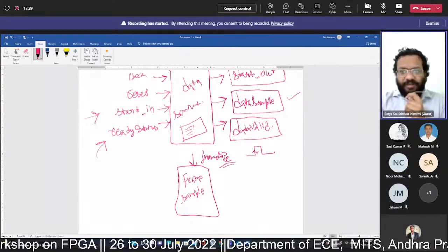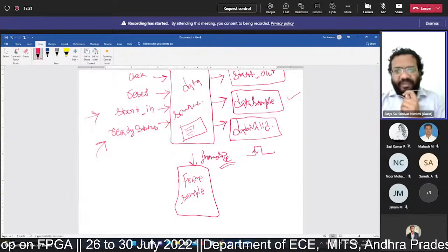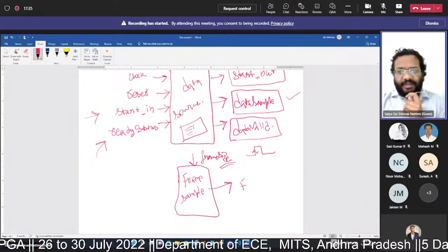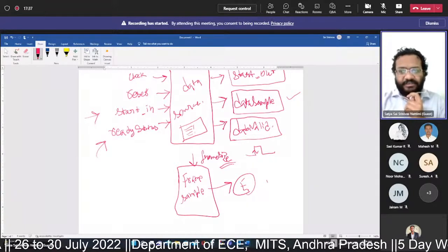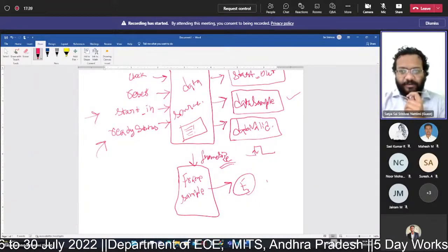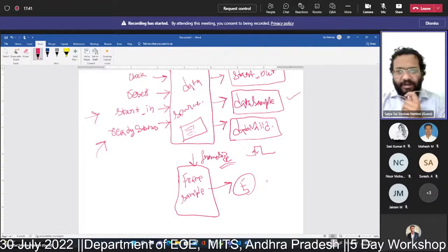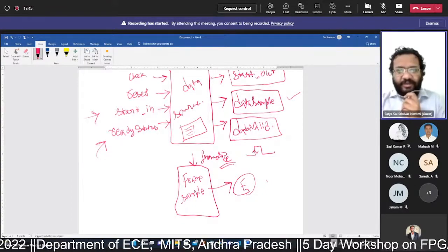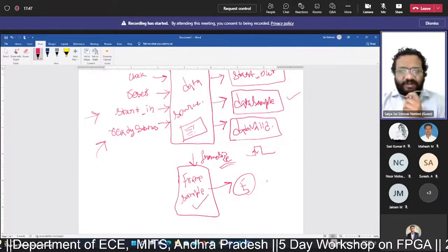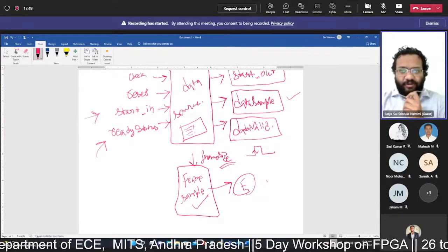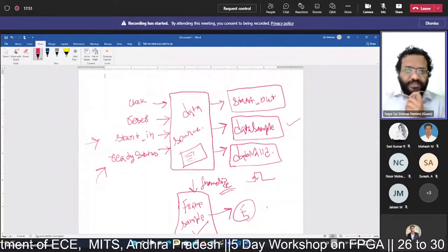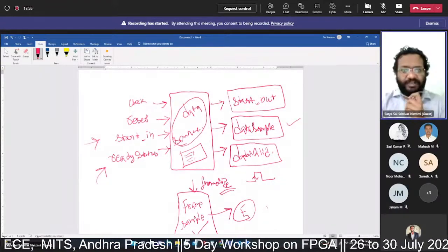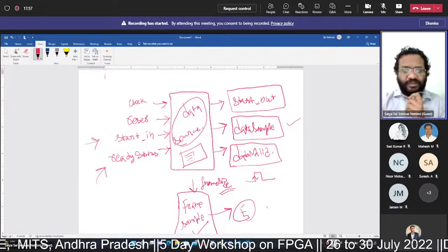Depending on the frame size, it collects that many samples and calculates the energy of the signal. This is one signal processing application we want to put on FPGA and verify. Our frame energy design is already ready, so we only need to make the data source ready. Once it is, we will integrate these two and put it on the FPGA.